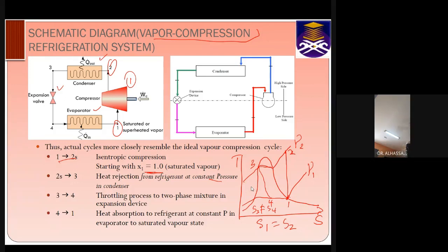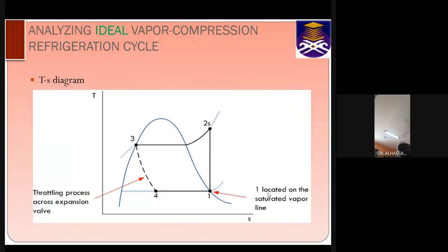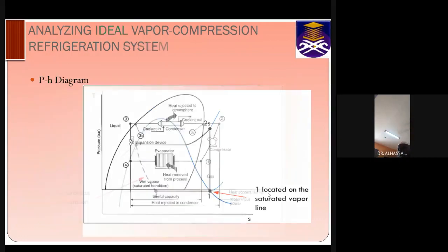Here we have the fluid which is at the saturated liquid state, and this fluid which is a saturated liquid vapor mixture. Because of this two-phase fluid, the entropy of the fluid is said to increase in this way. Okay, so this is the clear diagram for the ideal vapor refrigeration cycle.